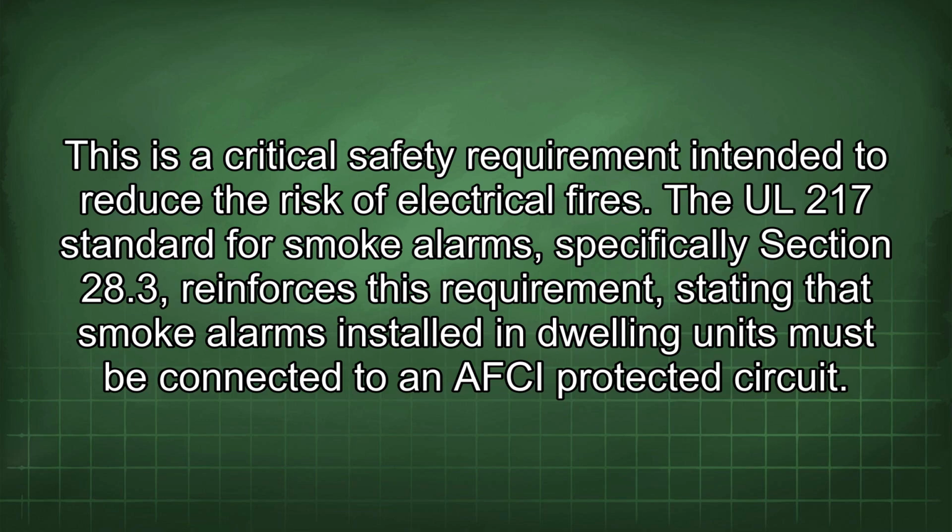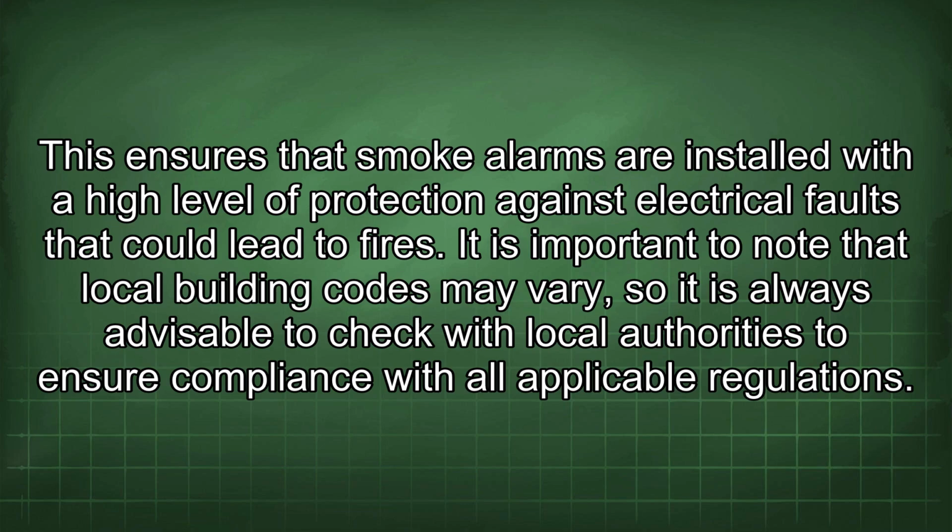The UL 217 standard for smoke alarms, specifically Section 28.3, reinforces this requirement, stating that smoke alarms installed in dwelling units must be connected to an AFCI-protected circuit. This ensures that smoke alarms are installed with a high level of protection against electrical faults that could lead to fires.